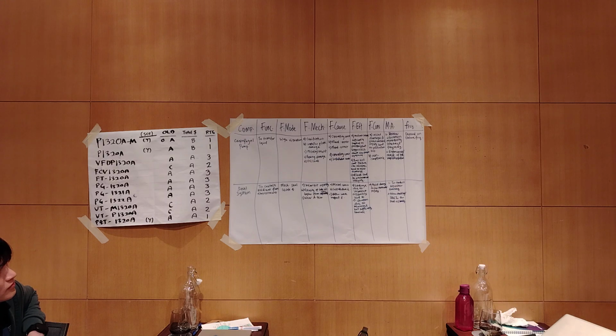If I do it every day, can my vibration improve? No, right? So there must be a time-based element that you have to monitor. It's not like you monitor on and off condition. You must have a time base to monitor it. A time base does not depend on failure frequency. The time that you fail is already too late. Due to high vibration, it's already too late. So you must have a time base to monitor your vibration.